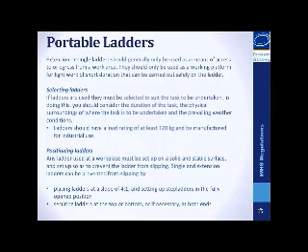Selecting the ladder. If ladders are used, they must be selected to suit the task to be undertaken. In doing this, you should consider the duration of the task, the physical surroundings of where the task is to be undertaken, and the prevailing weather conditions, if applicable at all. The ladder should have a load rating of at least 120 kilos and be manufactured for industrial use.